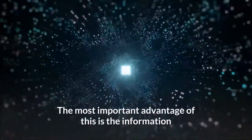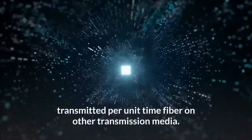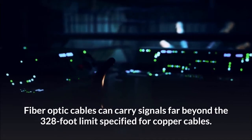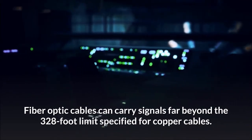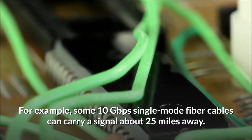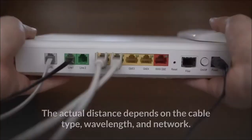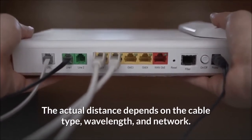The most important advantage of this is the information transmitted per unit time over fiber compared to other transmission media. Longer distances. Fiber optic cables can carry signals far beyond the 328-foot limit specified for copper cables. For example, some 10 gigabits per second single-mode fiber cables can carry a signal about 25 miles. The actual distance depends on the cable type, wavelength, and network.